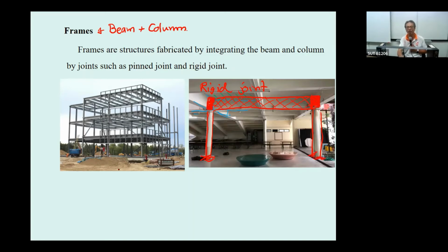And another one over here is the steel. Okay, and for the steel section, the joints may be the pin. You are an engineer, okay, many times you have a chance to design a simple steel frame. When you design a simple steel frame, you may have a chance to do the modeling of the structure. You can model the support to be the pin, or you may model it as the fix.